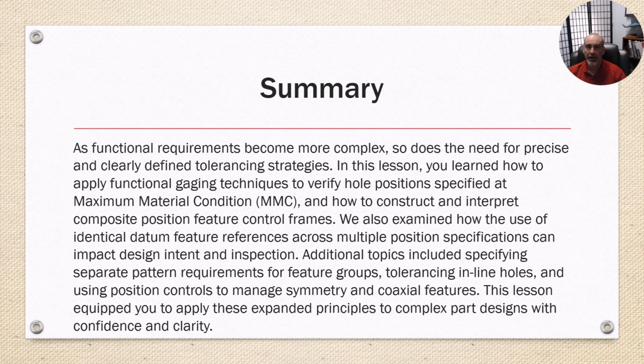In summary, as functional requirements become more complex, so does the need for precise and clearly defined tolerancing strategies. In this lesson, you learned how to apply functional gauge techniques to verify hole positions specified at maximum material condition, or MMC, and how to construct and interpret composite position feature control frames.